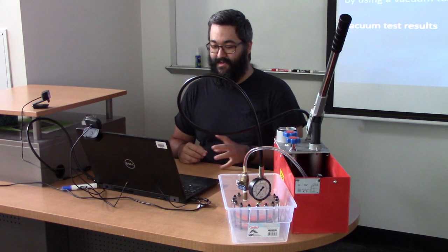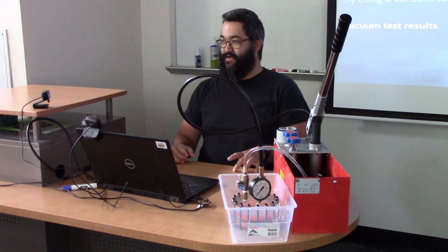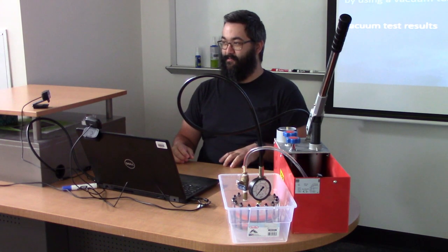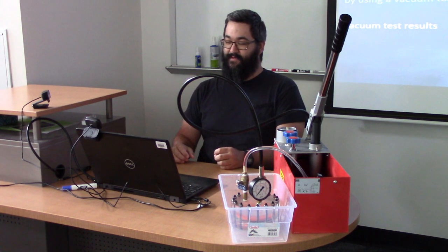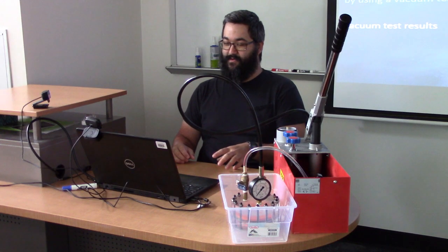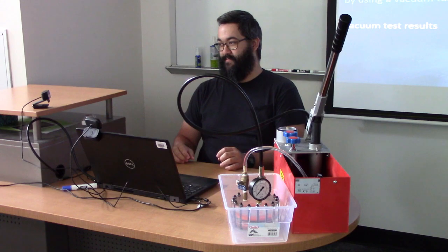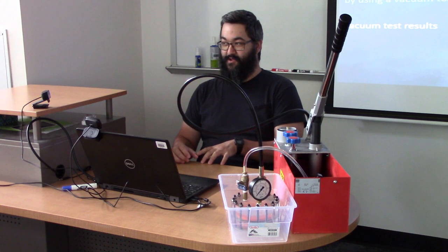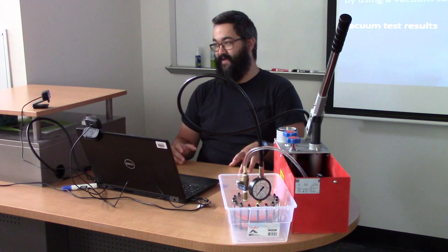So it controls the amount of material at a constant speed. So it doesn't slow or increase the printing time. All we're doing is changing the volume of material coming out of the hot end. That's kind of the nice thing about slicer software. It takes those parameters and calculates them out. So you can tell the printer, hey, I want you to move 50 millimeters a minute or a second, or whatever setting you want to use within the slicer, and then it will take all your other parameters that you change and calculate what it needs to do to be able to move that fast.